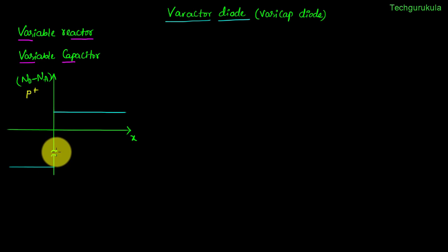These lines indicate that there is a lot of range in the middle, which indicates that the doping we have done is high. And this side is N and the doping is like this. This looks exactly like what we have discussed previously. If the doping profile is like this, we can say it is an abrupt junction because the doping concentration is changing abruptly at the metallurgical junction.